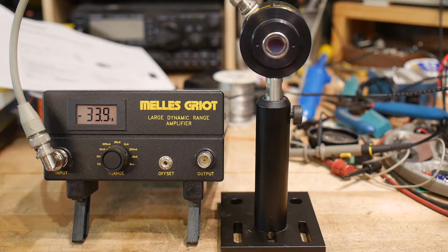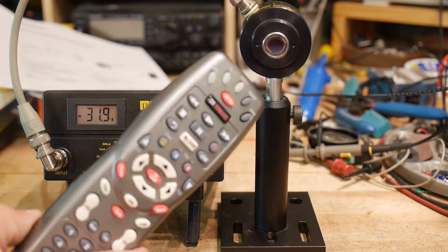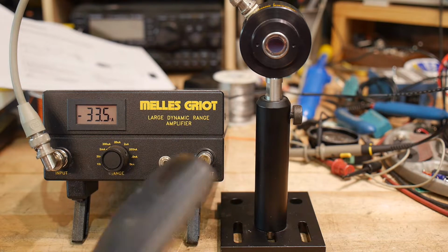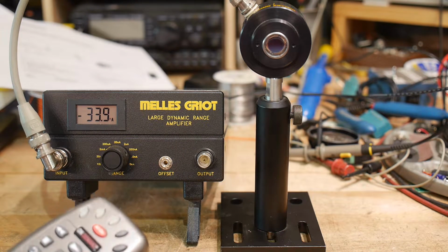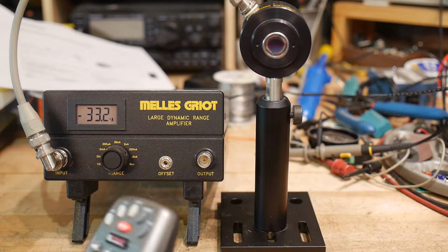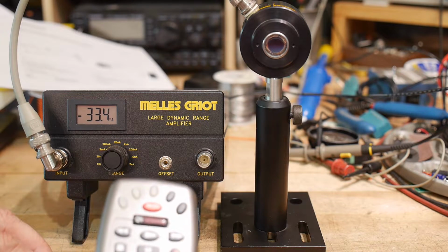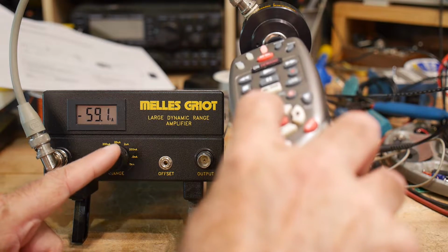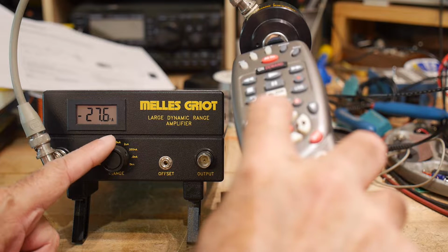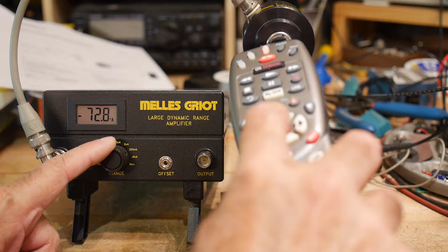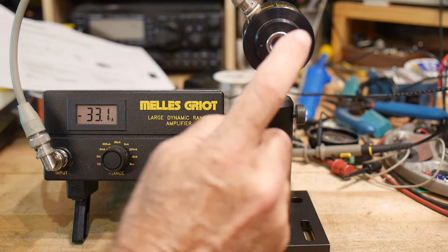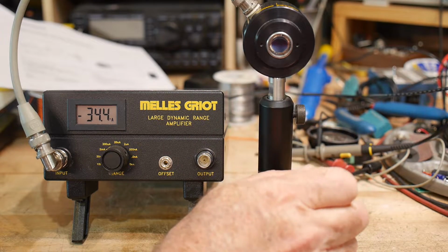All right, so this is an old remote control that I have. I was about to throw it away and I thought, no, maybe I can measure it, do some things with it. It has infrared light, and if I hold down a button and put it next to the photodiode, you can see that we went from 28 microamps up to 90 microamps. So this is outputting light, at a frequency that I can't see, but the photodiode can see.